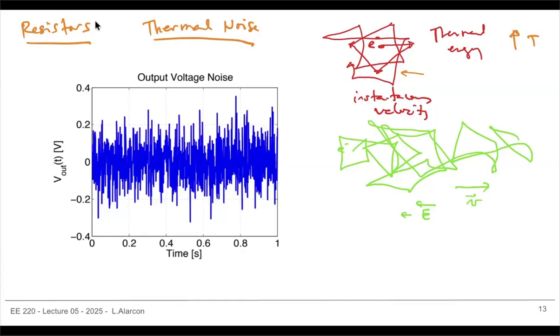But just off the bat, as you can see, if the signal that I want is less than the noise signal generated by your own amplifiers, then you're not sure if at the output you're actually amplifying your input signal or you're just generating or outputting the noise of your own amplifier.